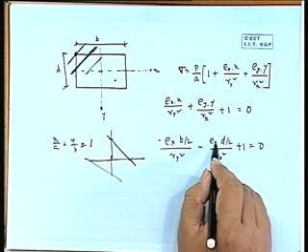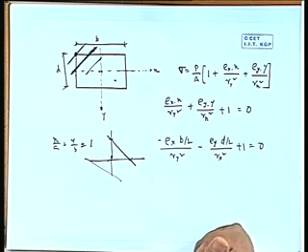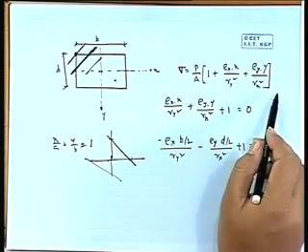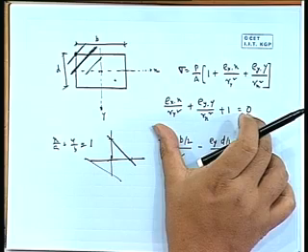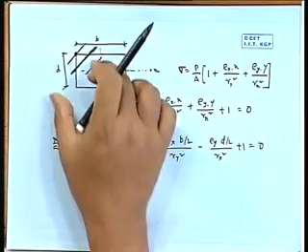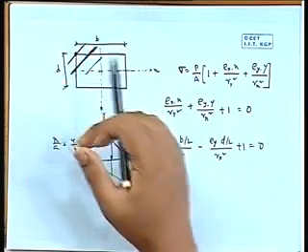Now from here we will try to get the value of the eccentricity ex and ey. Since we have written the general expression for sigma, now if we make sigma equal to 0, then we are getting this equal to 0. So that will give the equation of that line. Now that line, if we want to keep it outside the column section,